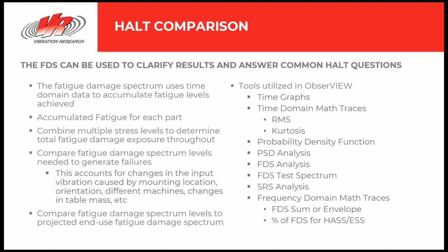Rather, we are looking at every peak to valley stress cycle for each individual frequency bin, calculating a damage number based on a material property and Q to accumulate damage in each frequency bin, and then drawing the lines in between. This allows for relatively accurate damage assumptions to be made for each individual frequency bin and then to generate a fatigue damage spectrum.